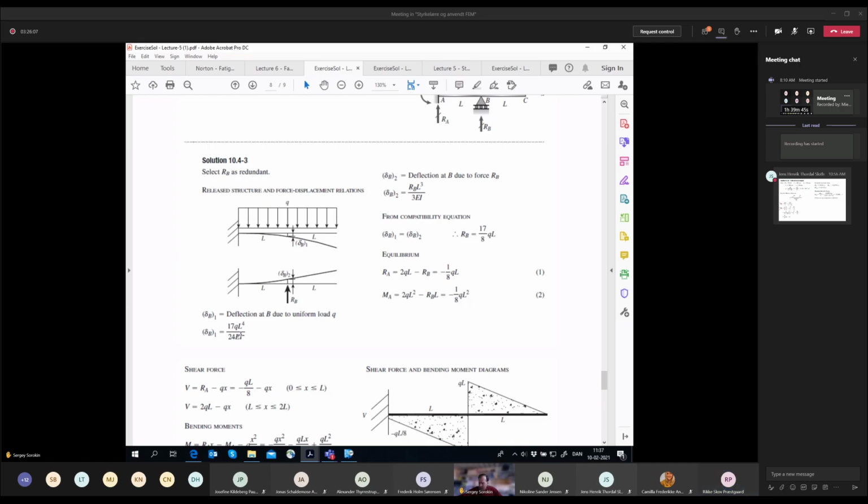Okay, so now the question is, how does this delta come into play? Probably it's closer to take case 5, when you have this P not at the end of the beam, right? There you have a cantilever beam and P is applied somewhere.